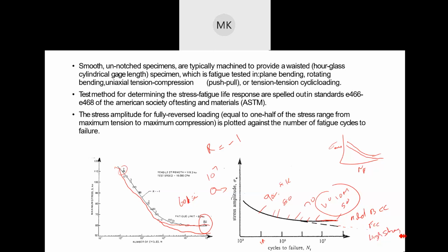The reason why high strength materials act the same is because of the additions that you have, let's say silicon carbide being added to a material or carbon nanotubes added to aluminum. All these things are going to increase the strength of aluminum alloy, but it also makes sure that the material doesn't have much saturation in terms of fatigue strength, because all these spots where you have the carbon nanotubes or any fibers added to the material could be the point where your crack can initiate in the material.